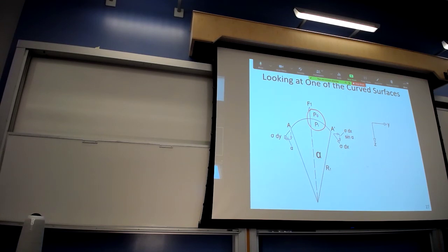And so again, what we can do is look at the difference in pressures across the interface, and we're going to multiply it by the differential area. That difference in pressure across the interface is due to the integration of the surface tension components acting in the z direction. There's no weight to worry about because this is infinitesimally thin.